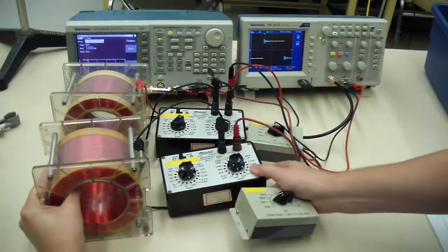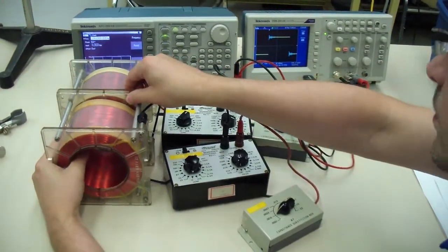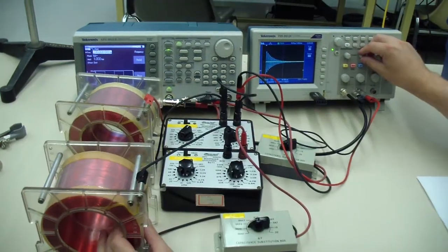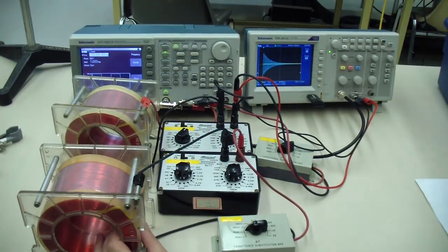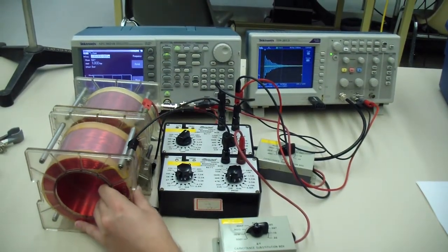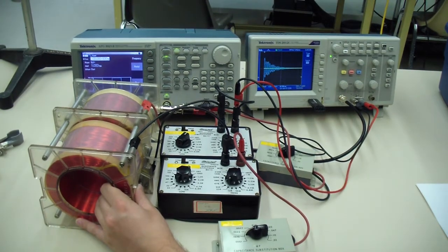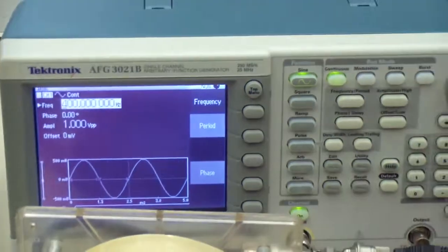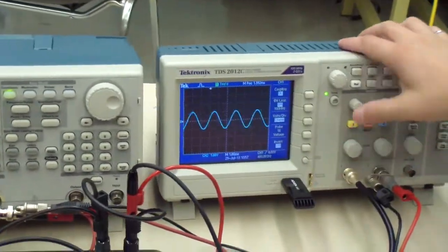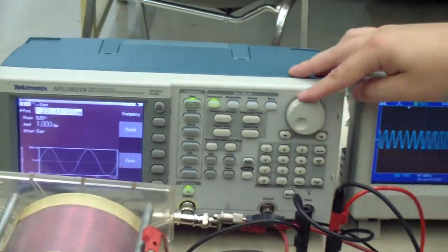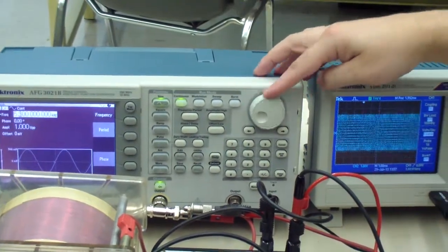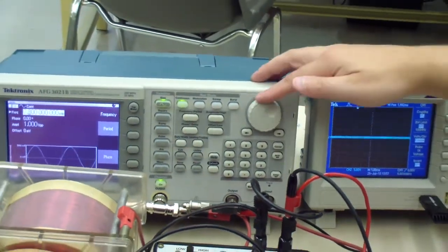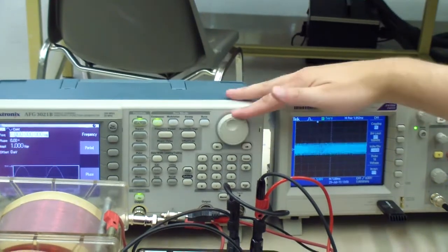Bring the other circuit back and place the inductors next to each other for maximum coupling. You may need to zoom in on the capacitor's decaying oscillations to see the effect of coupling the inductors together. Change the function generator to output a sine wave. Disable the display of the original signal and sweep through a wide range of frequencies. This will allow you to find one of the normal modes and thus establish the general frequency range in which to record.